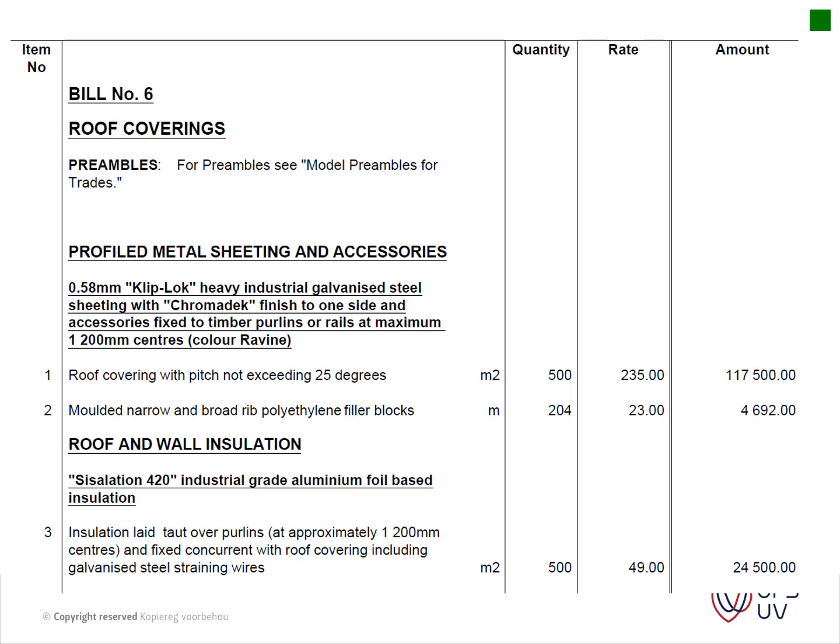Then our bills of quantities. Very important to note is that we've got bills of quantities. So our bills of quantities comprises many bills divided into trades. So now you've got your trades of earthworks, your trade of masonry, roof carpentry, which includes your roof construction, except if it's steel construction, then it will fall underneath structural steel, for instance.